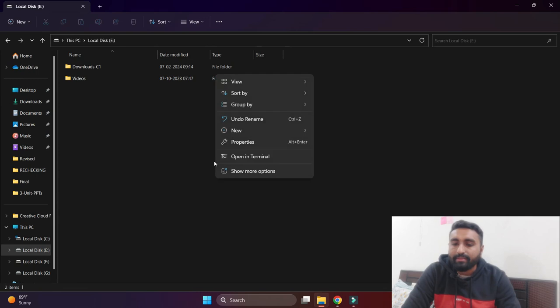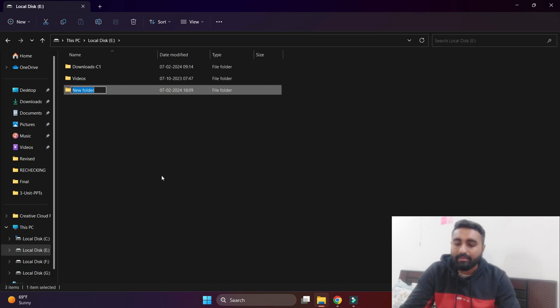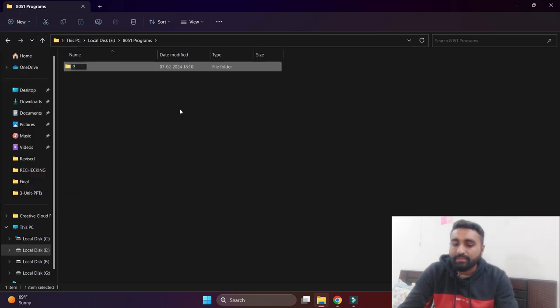Now I will teach you how to start this Keil uVision software for writing programs for the 8051. Whenever you want to make any program, my simple advice is to make a folder in which you are going to make the program. Let's say in this E drive I am making a folder for my 8051 programs. In this folder I'm going to make a new folder, and I'm giving it the name program 1. Okay, so this is the folder that I have created. So always create a new folder, and create the new program only in the new folder, right?